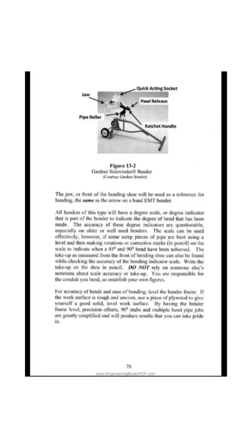Write the take up on the shoe in pencil. Do not rely on someone else's notations about scale accuracy or take up. You are responsible for the conduit you bend, so establish your own figures. For accuracy of bends and ease of bending, level the bender frame.